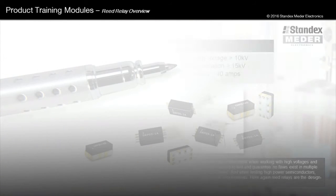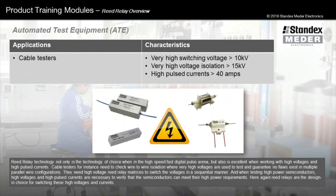Reed relay technology not only is the technology of choice in the high-speed, fast digital pulse arena, but also is excellent when working with high voltages and high pulsed currents. Cable testers, for instance, need to check wire-to-wire isolation, where very high voltages are used to test and guarantee no flaws exist in multiple parallel wire configurations. They need high voltage reed relay matrices to switch the voltages in a sequential manner.